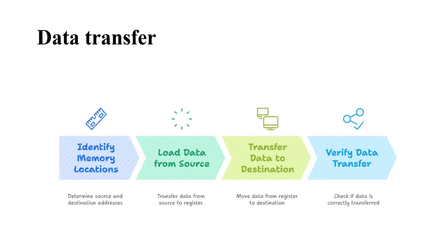We will take the inputs and those have to be transferred to another external memory locations starting from 4000H to 4009H. This program operates in a loop transferring a specified number of bytes from the source to destination. Here I have considered the number of bytes to be transferred as 10. You can change accordingly, that can be varied.